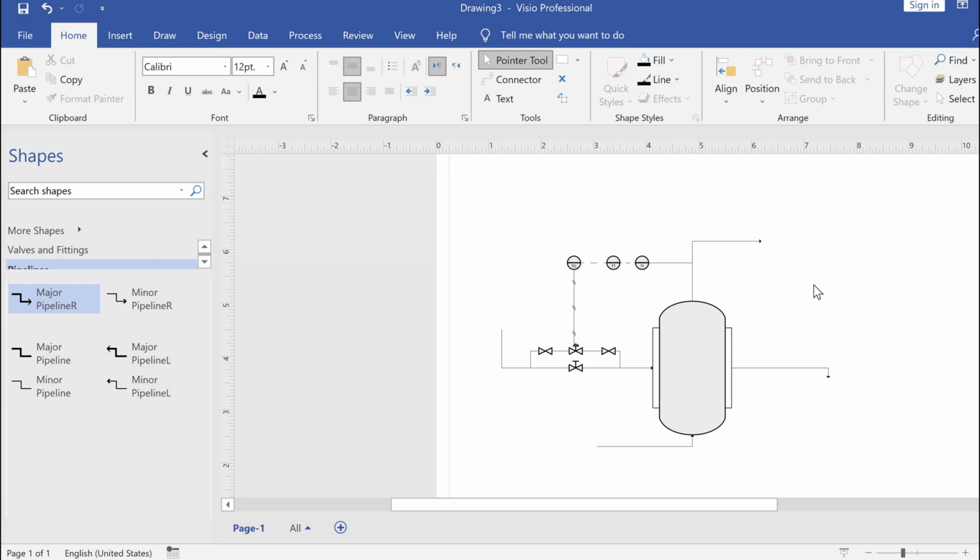So we add or we install a temperature indicator on that stream, which is right here. Now this temperature indicator will indicate the temperature of the stream leaving the reactor. And then the indicator will send an electric signal to the transmitter. The transmitter will send another electric signal to the temperature indicator controller. This controller, it will order a valve a certain order depending on this temperature.